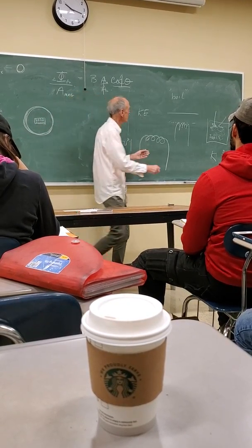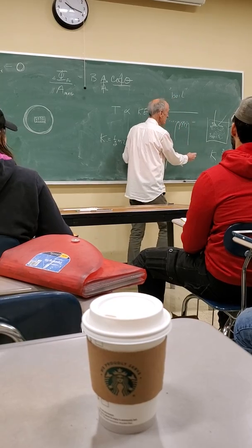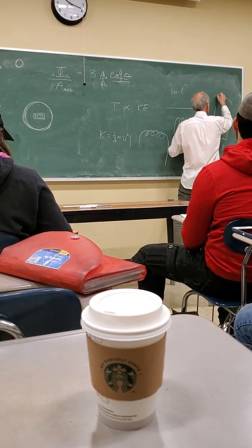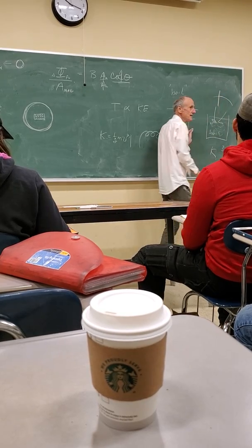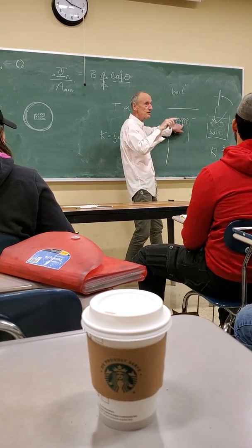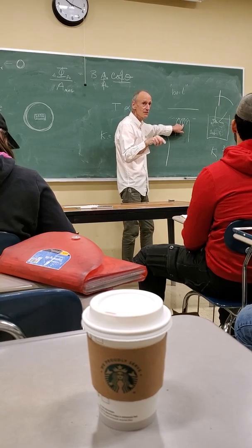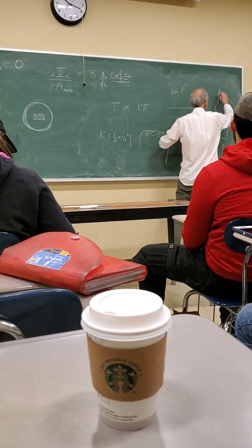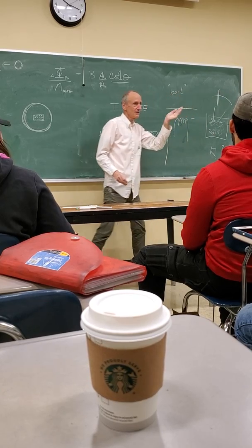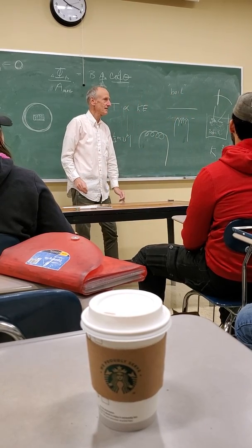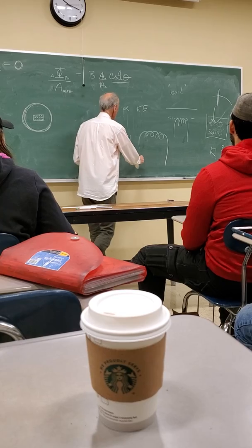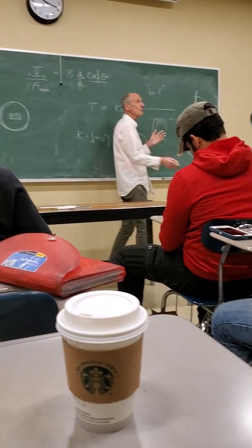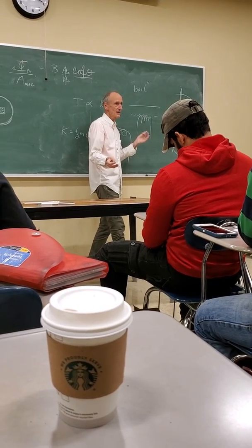But some of you got confused. Once we set this, you saw the current in the filament went up and then went back. That was one of the questions, and that's because the filament, when it's cold, has a low resistance, right? You answered that question. And so it gets hot and it gets stable, and we never touched that. We never adjusted that. So we have this hot filament boiling electrons off in all directions, not in one direction.